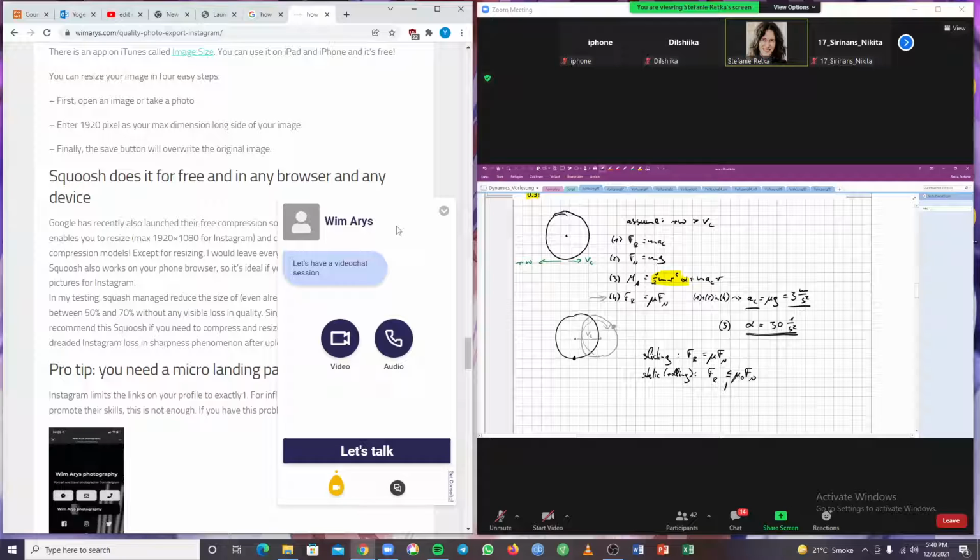And we can only transform this into an equal sign in the limiting case, when it's asked for the minimum friction coefficient or the maximum driving force or the maximum angle of inclination, these kinds of things. Only when we have such a question, we can use the equation of static friction and convert the smaller or equal into an equal sign.